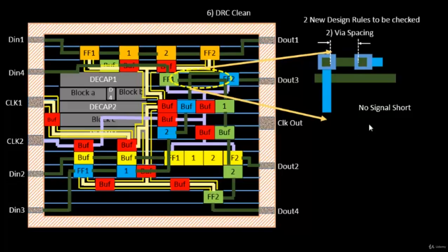There is one more rule, which is the wire spacing. The minimum spacing between these two wires should be at least this much. It can be more than it, but it can't be less than this, else it can't be printed. So it's more about printing: how do we print what we see on the layout. This has to be laid out onto silicon, and that is done using lithography techniques, which come up with some rules that the routing algorithm needs to follow.